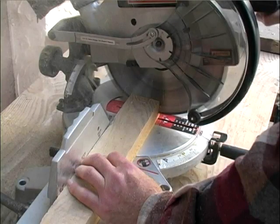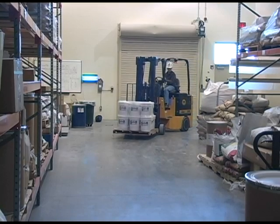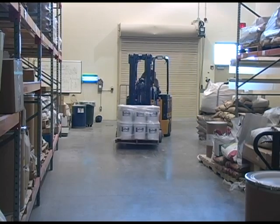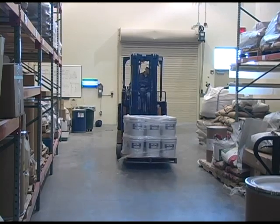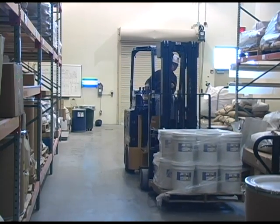For instance, the manufacturer of this saw recommends that workers protect their hands by keeping them at least 6.5 inches away from the blade whenever it is spinning. As another example of safe work procedures, forklift operators must keep loads low while driving to reduce the risk of tip-overs.